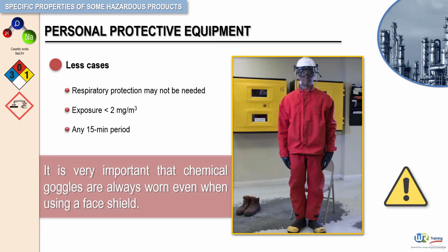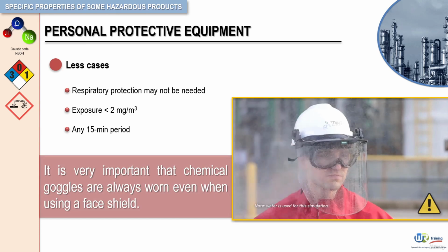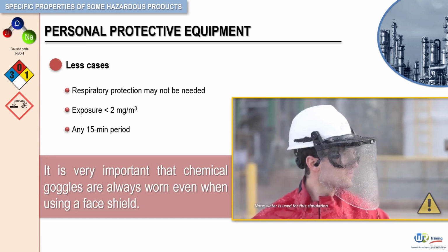It is very important that chemical goggles are always worn even when using a face shield. There is a natural tendency to turn the head quickly when sprayed in the face, exposing the side of the face and eyes if not protected.